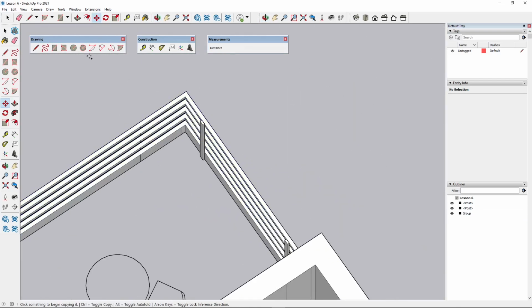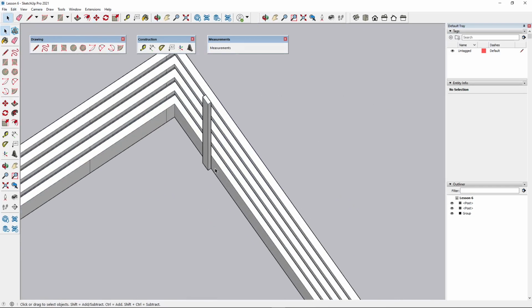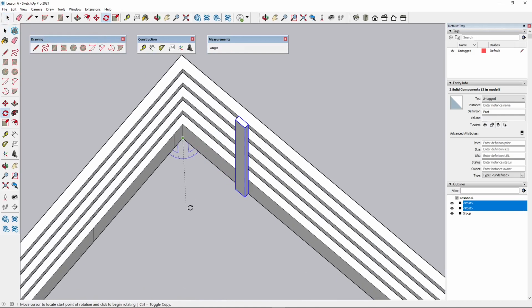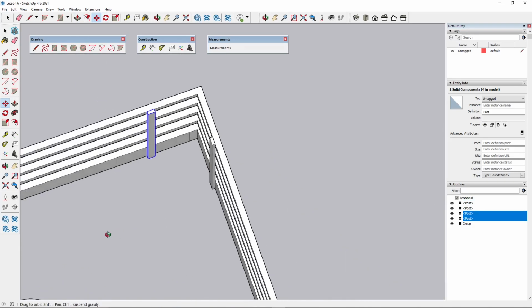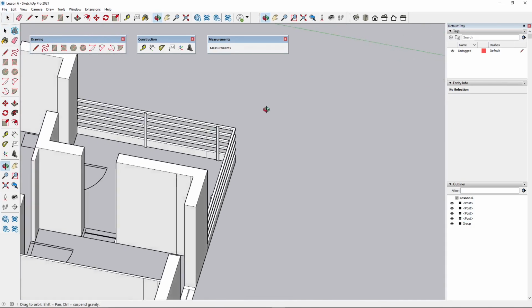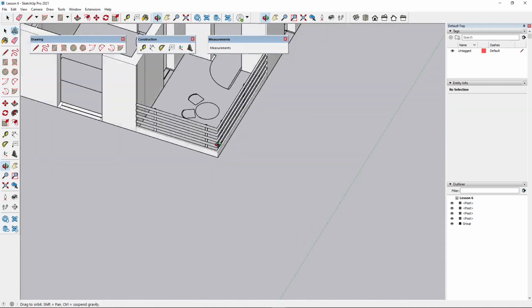And then I can use these two. So I will select the first one, second one, rotate, use that as the pivot. Click there, rotate, and hold, well, click Control and place it right there. Okay, but then I have to move them forward a little bit, like that. And there you go. So you can see how you can quickly add details to your architecture here.